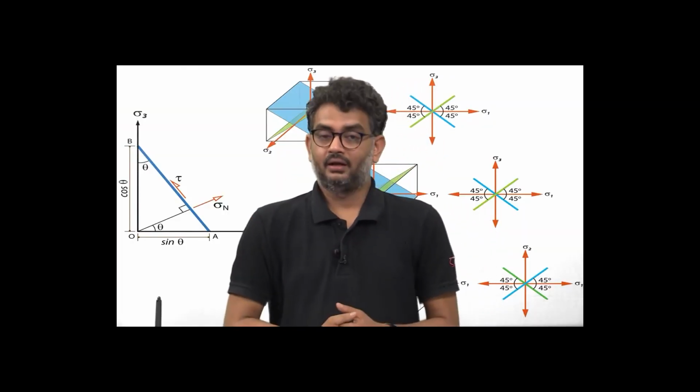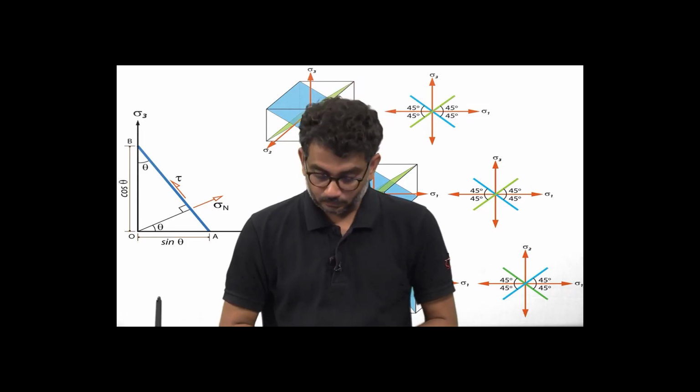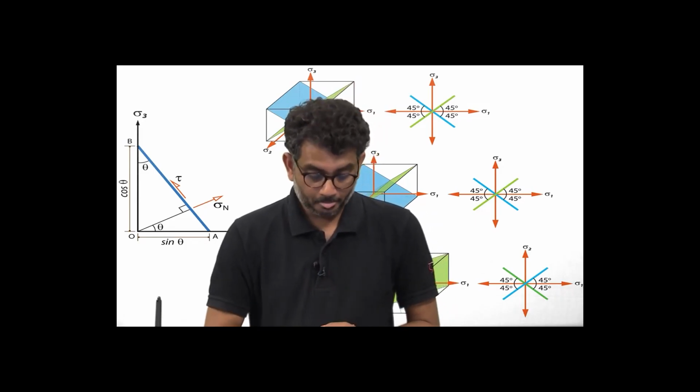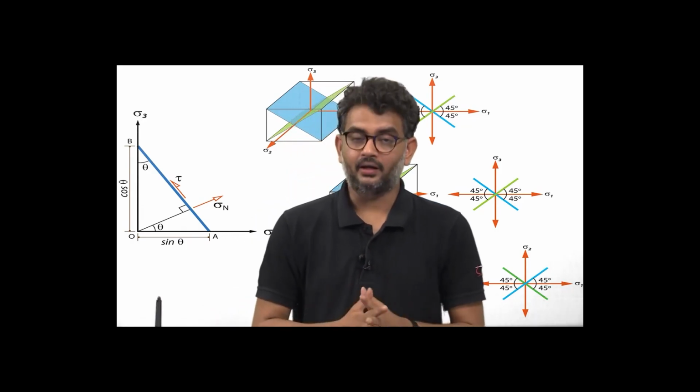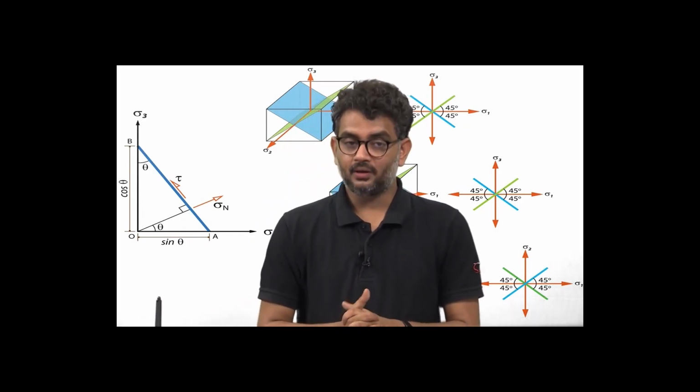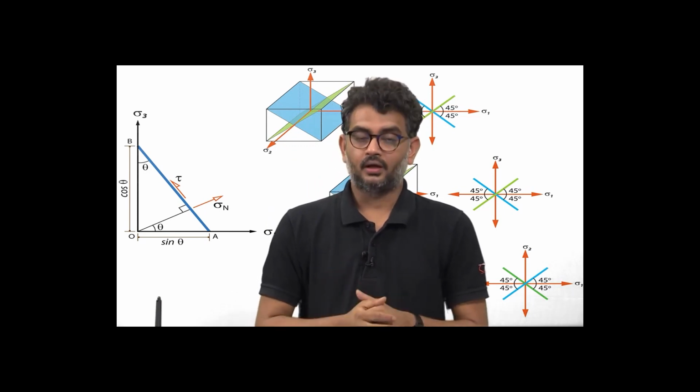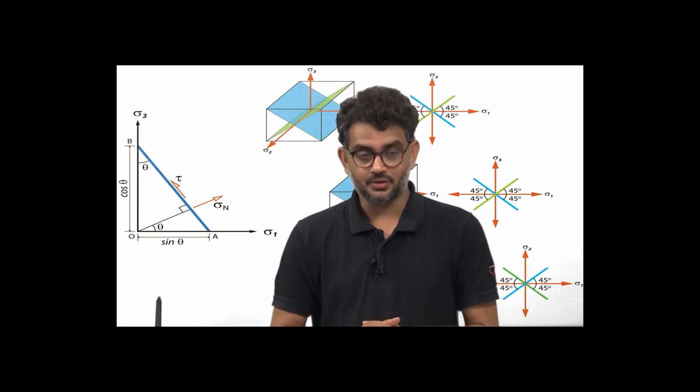So in that case, x, y and z are your eigenvectors, and the eigenvalues for y and z would be 0 because they are not getting stretched, but for x, with each increment you are deforming, it would maintain the same direction, but it would keep increasing with the same factor. Now this concept is applied for calculating the principal stresses and also the principal directions of stresses.